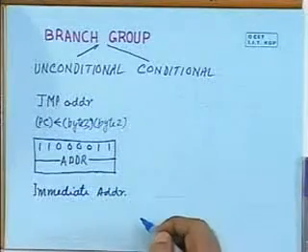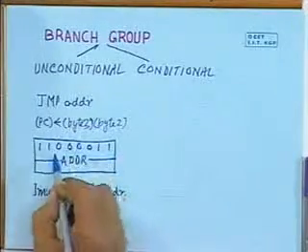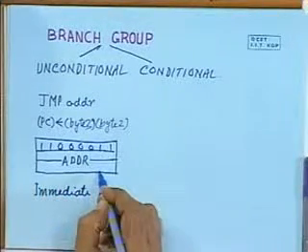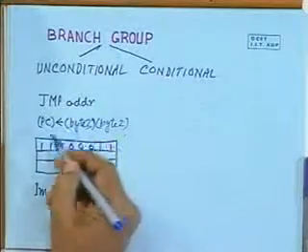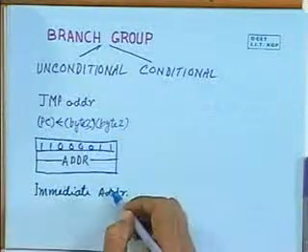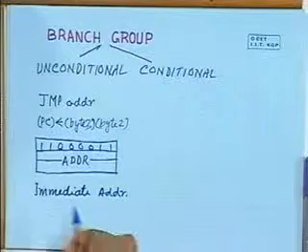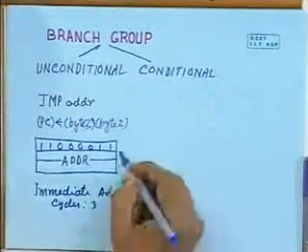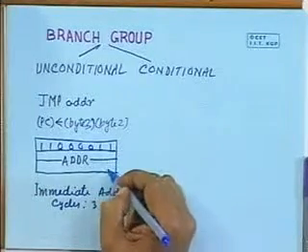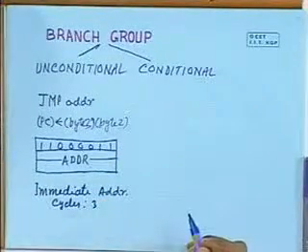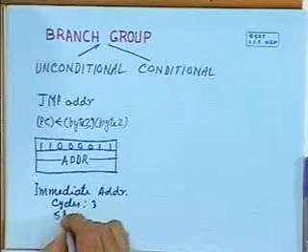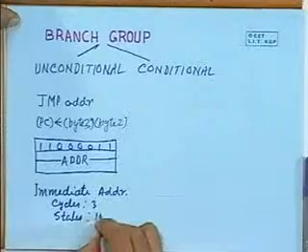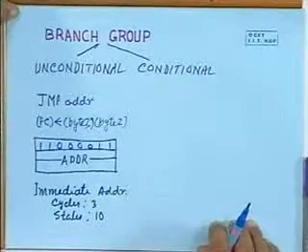So how much time will it require to execute? First of all, the instruction fetch will take place, and then these two address bytes are fetched and loaded into the program counter. That is what the instruction does. So it will require 3 machine cycles: one to fetch the opcode, and the next two to fetch the address bytes, which are then loaded into the program counter. The number of states required will obviously be 4 plus 3 plus 3, that is 10.